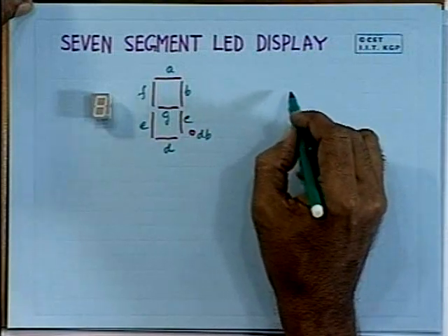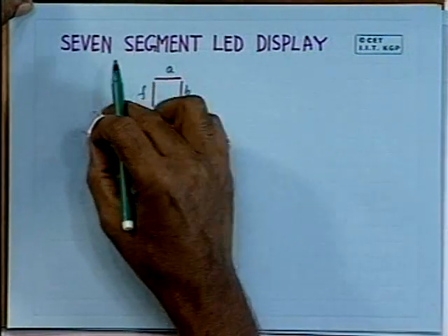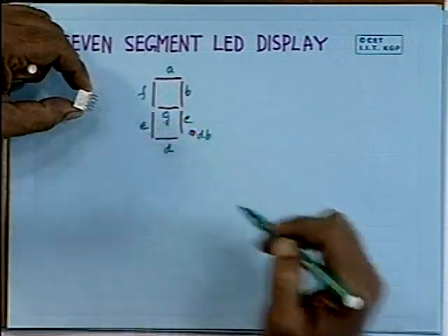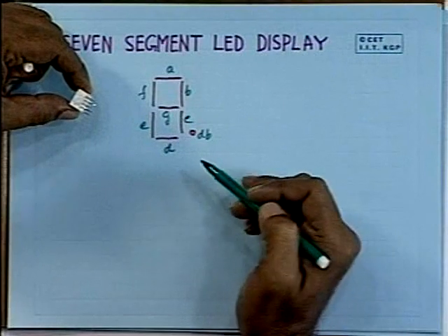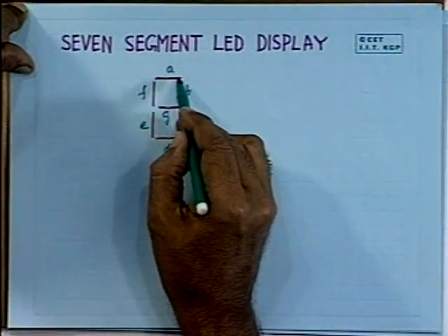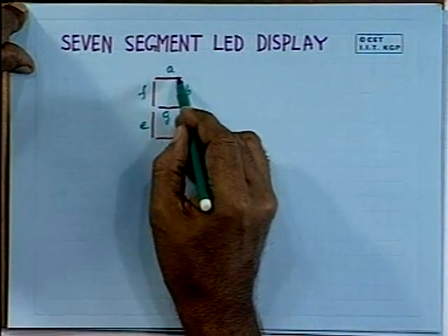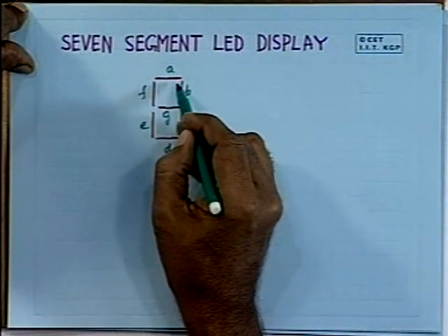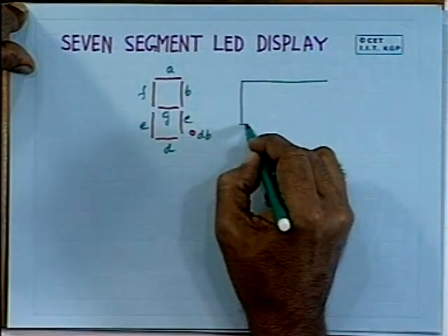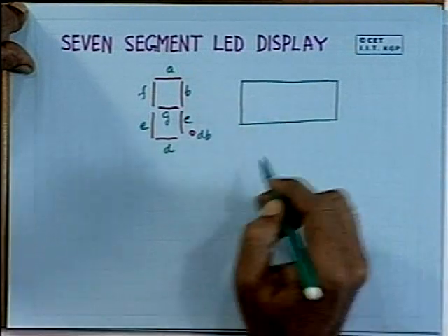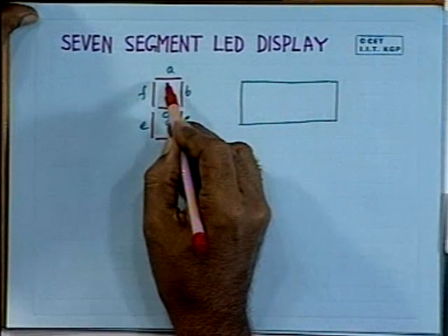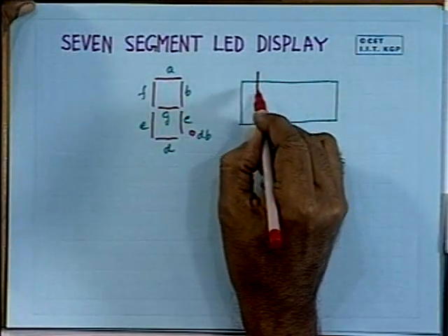Now, this particular IC package is available. As you can see, there are 5 plus 5, 10 pins. You have to make use of these 10 pins so that you can use any one of these segments. Essentially, each segment represents one light emitting diode. So, inside the device, the connection is somewhat like this. Say you have 8 LEDs, 7 plus the decimal point. So, 8 LEDs are here.